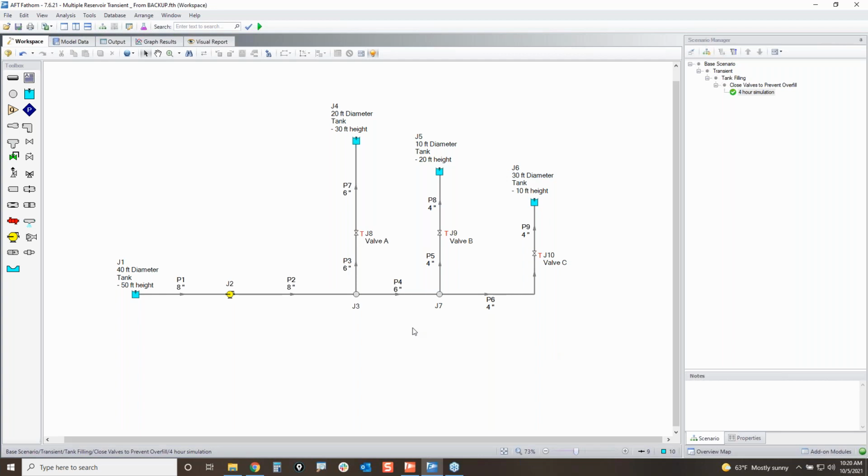And then one other tip, don't ever work on, run, or save model files over a network server path. Never do that. That is a major cause of file corruption, because if you have a very, very slight hiccup in connection to your network server while you're saving, that can cause file corruption right there as well.